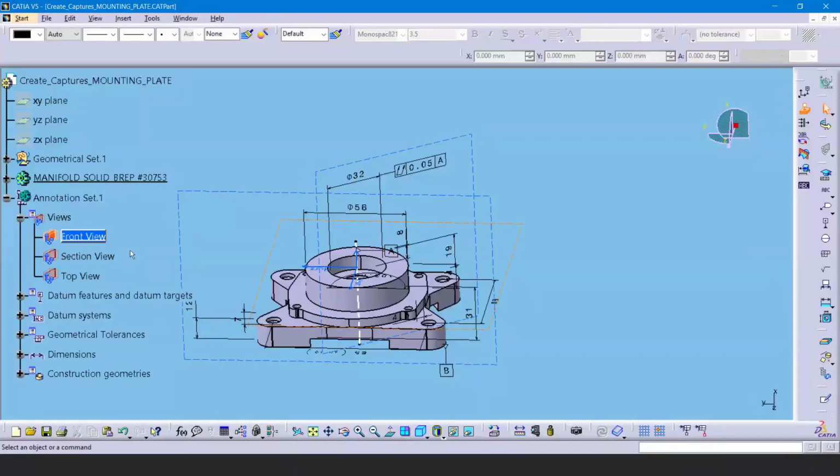What I first want to point out is the proper way, the way that requires you to not have to edit as much later on. The proper way is just to be cognizant of your double clicking. If you're in CATIA at all, you know that double clicking can sometimes change things and can sometimes break things. We're dealing with an active view when we create things in the 3D FT&A workbench, and the active view is changed with a double click. So if I double click here, I've now changed the active view. If I double click here, I've changed it again.